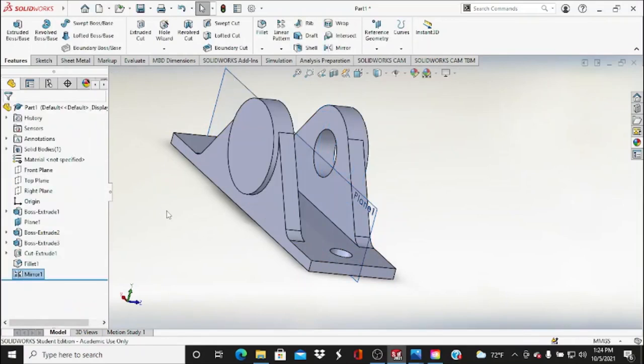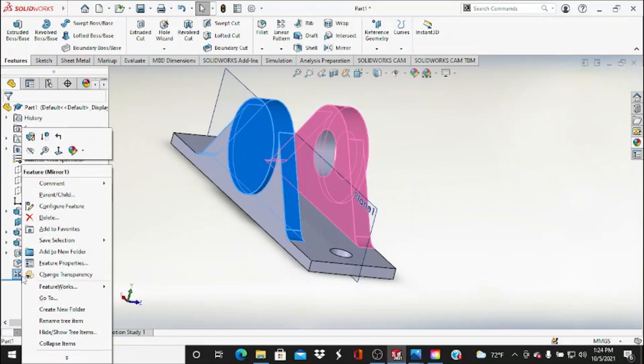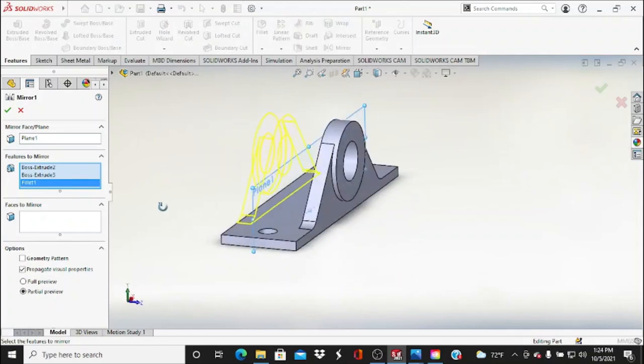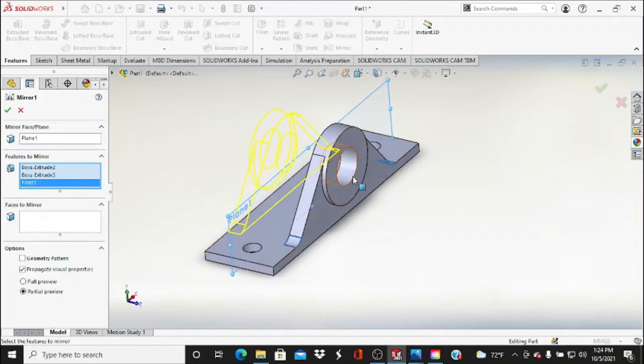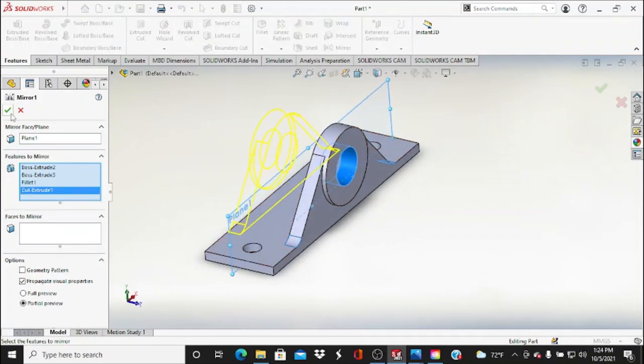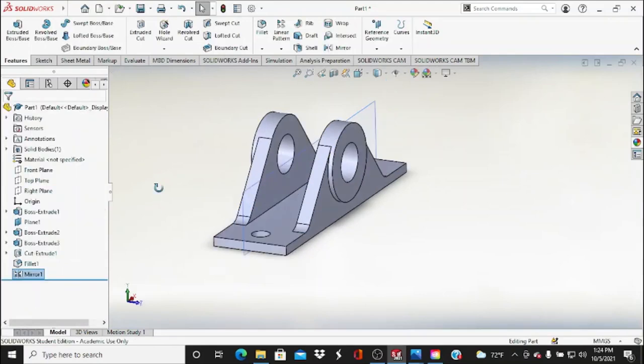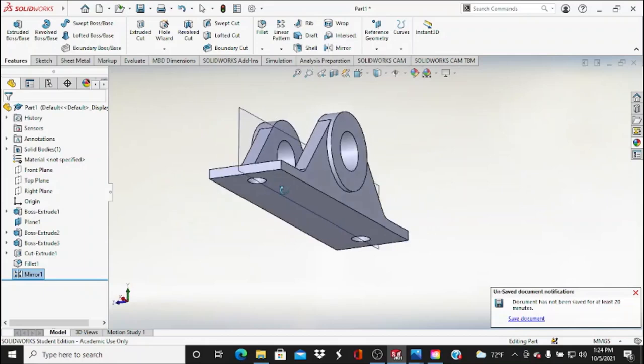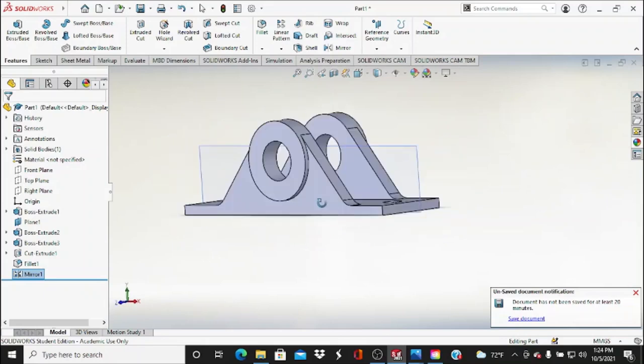And it should automatically, whoops, see? You have to be careful on these ones right away too as well. It's kind of tricky. So I'm gonna go back into this one and re-edit it. We forgot about this guy right here, this little inside arc. There we go. Check it, and it should automatically select the whole thing. There we go. Now we made a part.